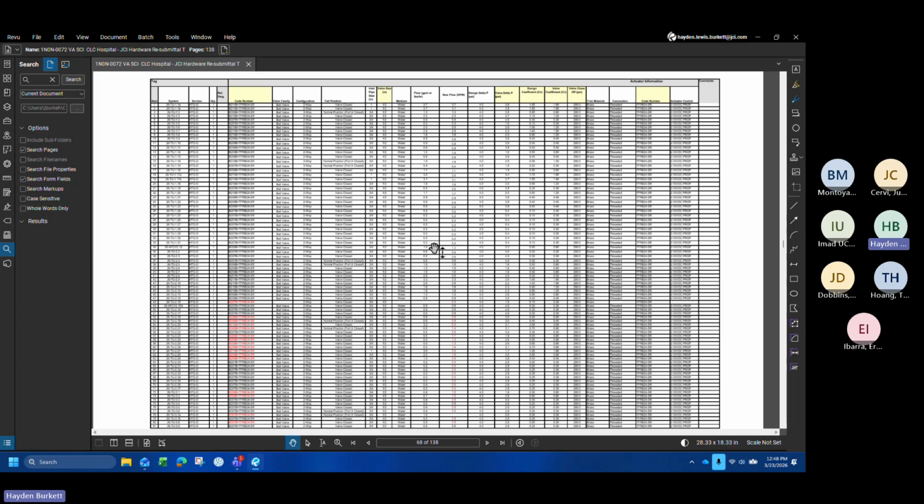If you just have a 2-position actuator, you just have a standard in and out. Whereas if you have your 3-way actuator, you've got your in and out, but you've also got a bypass when the valve is shut. You're going to bypass that water from the supply directly into the return, and then it's going back to the loop.